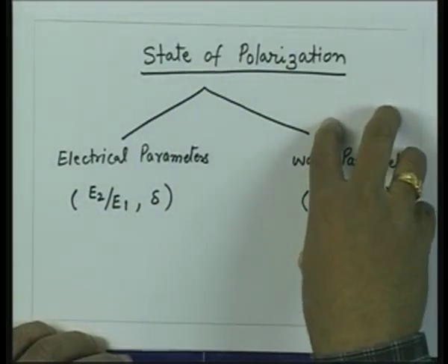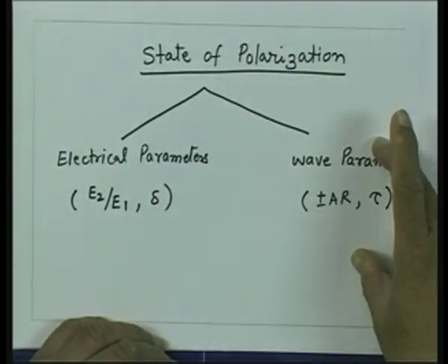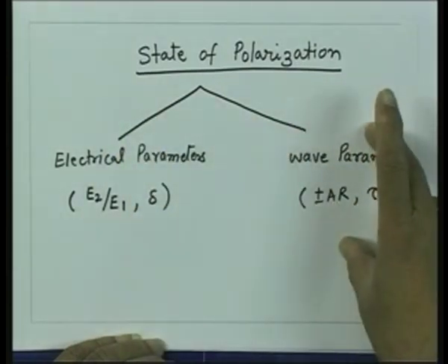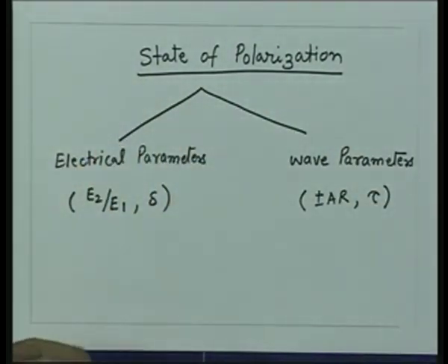So, for generating a particular shape of ellipse or a particular wave of that elliptical polarization, one would ask what parameters should be set electrically while generating this wave. So, we would need a relationship between this and this. Conversely, one can ask a more analysis-type question: if I had two linear polarizations, vertical and horizontal, and I excite them in certain proportion with certain phase difference, what kind of ellipse will be generated? So, this problem from here to here will be more like an analysis problem, but from here to here will be more like a synthesis problem, because this will define the need which we want for polarization, and then we would ask what should be the electrical system parameters so that that particular state of polarization will be generated when the wave is launched. So, we will see the relationship between these two parameters.